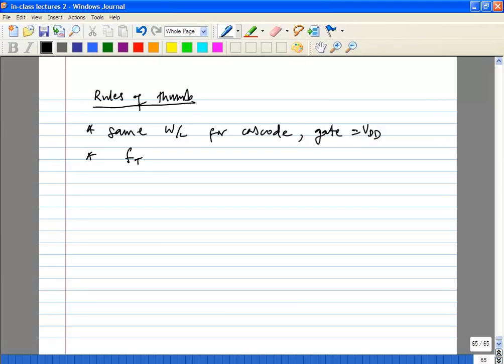Yes, but I'm choosing W to also make a normal transistor. If it comes out to be a large W, I will not use the same large W there. Why not? Start with what? The thing is like this: the larger you start off with, the more headroom you will have for your main transistor, and the better the IIP3 you will get. You will make the decision to reduce it only after you are sure you meet your IIP3 requirements, right? When you start off, you don't know what your IIP3 is. You don't know anything about the LNA, except that you know the noise figure and the power consumption. Those two things you know, but you don't know much more.